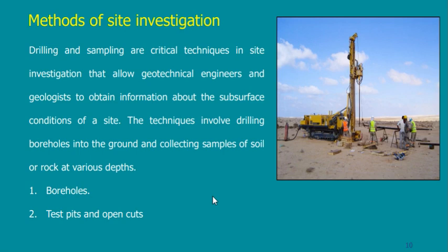So taking a sample from the ground may affect the shape of the sample. It will not affect the material usually, because the material is sand. It will be sand. I will not take sand from the ground and on top it will be clay. It will still be sand. But the degree of the compactness of the sand will change.